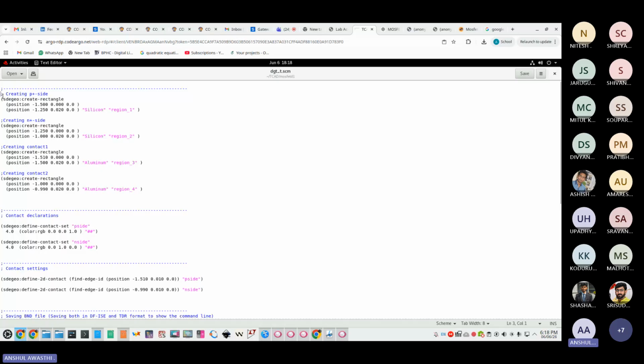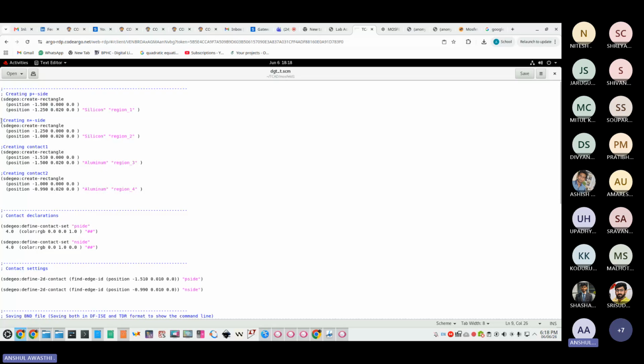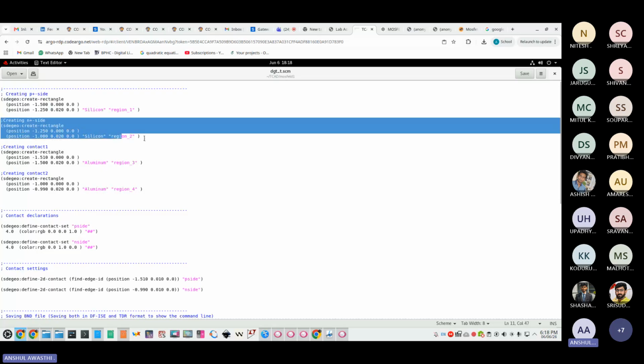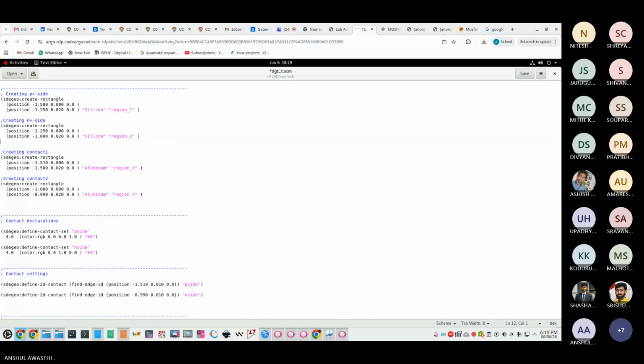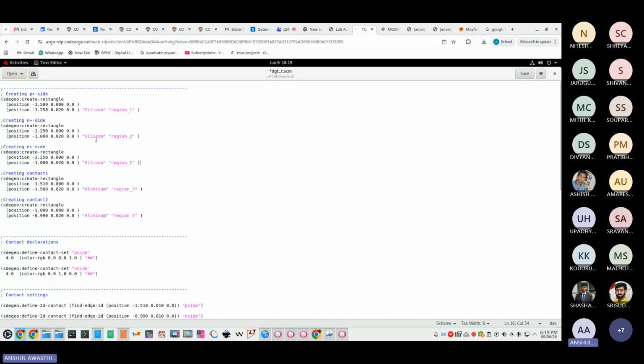So what I'll do is copy one more silicon region, and that to the N side because it is an NPN transistor. So I'll just copy this N, Ctrl+V. So now I have 3 silicon regions. First of all, I'll define the 3 silicon regions. Let us start from 0, 0, 0.